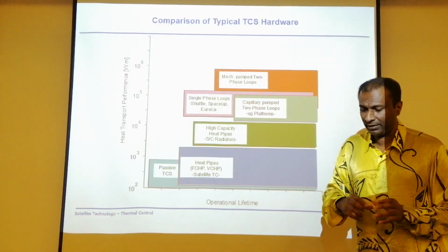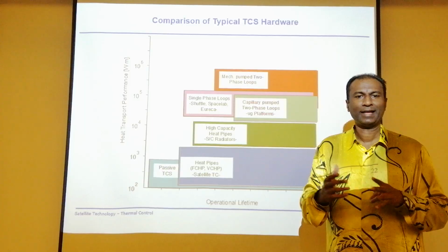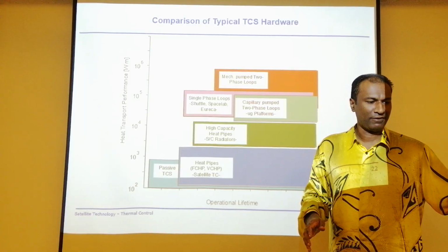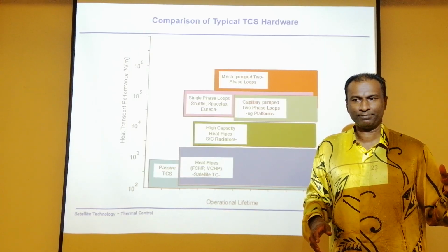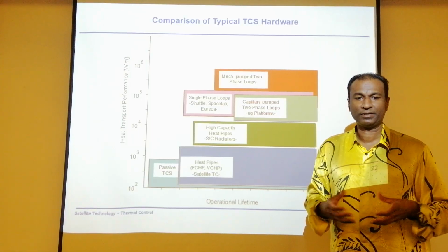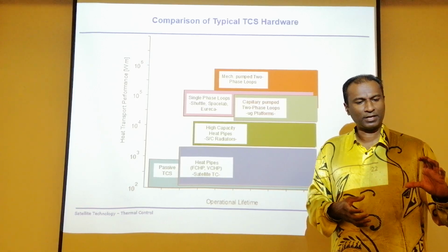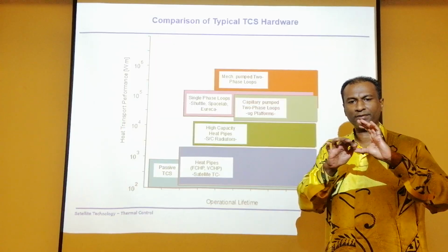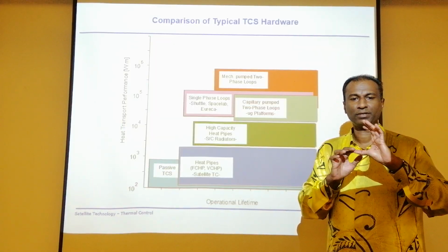There are two ways you can do this. One, let it happen naturally. How it can happen naturally is that when you have heat at one spot, that spot will get heated up. We have a very special kind of design, capillary designs. If you look at the actual cross section of that duct or pipe, you will have grooves. These grooves on the wall are going to give you the capillary effect.